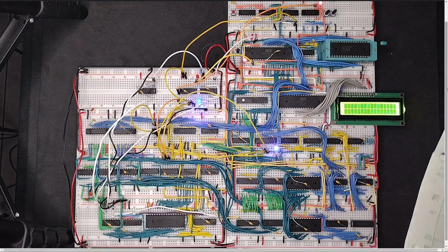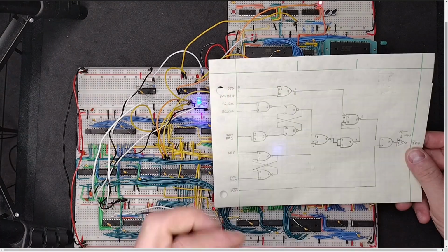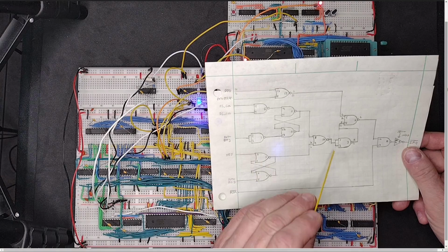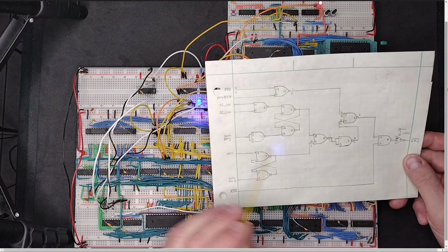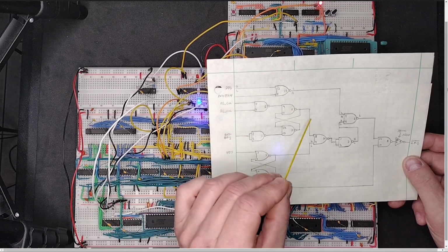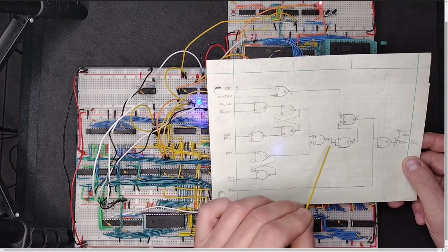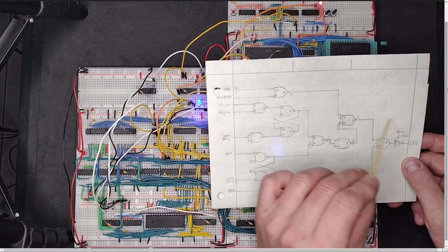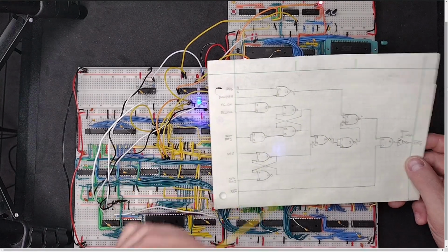So I was able to do that with just adding a couple of gates to a couple of chips in my system, because I'm using the actual gates to do inverters. So I have an inverter here, which is a NAND gate. I have another inverter here, which is a NAND gate. So you can see here, I need 3 additional chips. I'm using this quad 2-input NAND gate chip. This is another quad 2-input NAND gate, and then these here are the NOR gates.